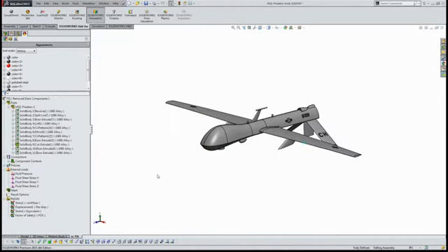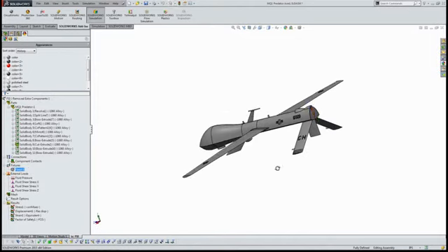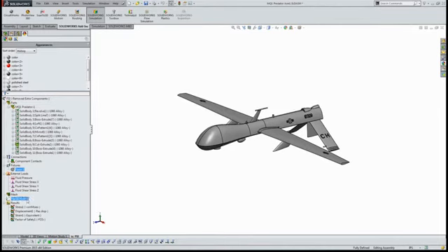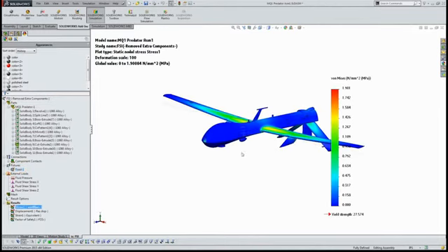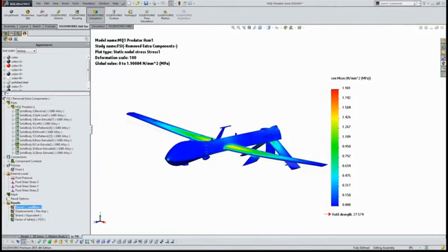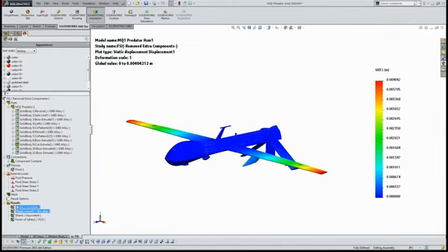And now, I said that this is a very basic setup. I just basically fixed this guy at 2 places, at the center up here and this back face. And now I can take a look at the stresses. Now this deformation is scaled about 100 times, but this is basically a fluid structure interaction problem, right? So I'm taking into account the pressures, seeing how much stress and displacement those are going to cause.